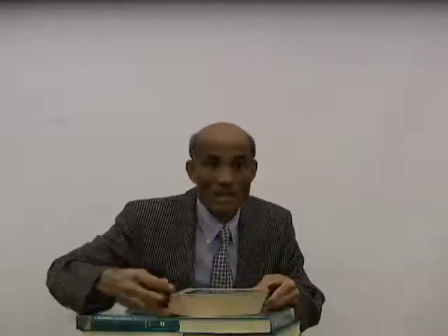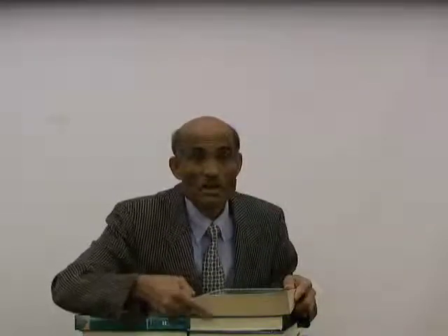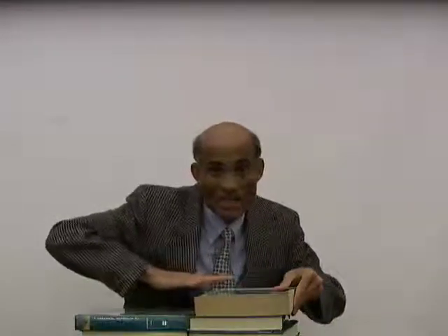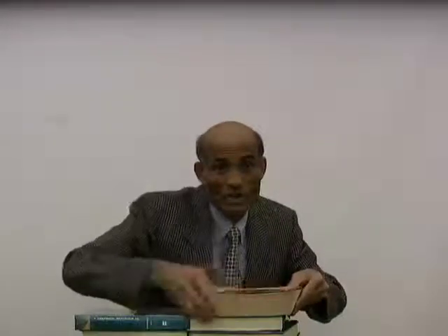Now, what happened here? There is a change in the angle. Before I apply the force, the edge of the book is vertical. This angle is 90 degrees. Now what happens when I apply a shear force? The force I'm applying is tangential to the top surface. Now what happens? The edge of the book is now at an angle. So this is the effect of a shear stress.